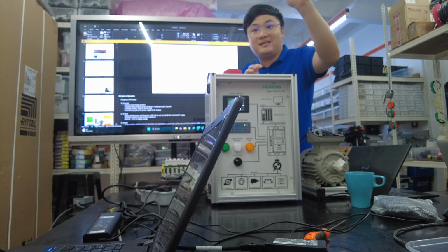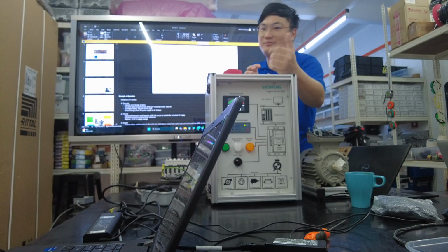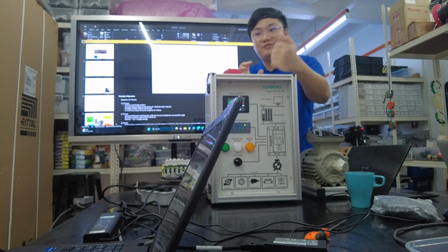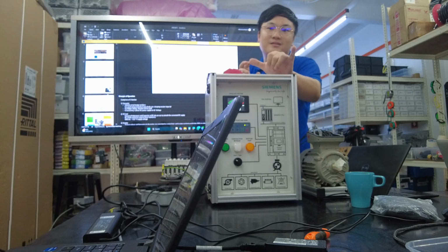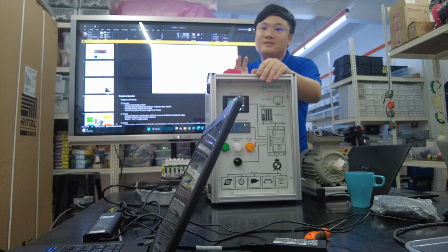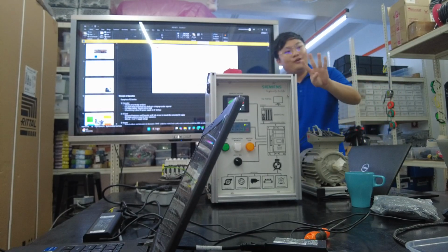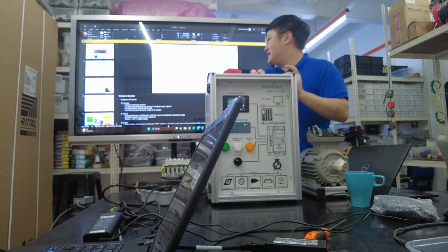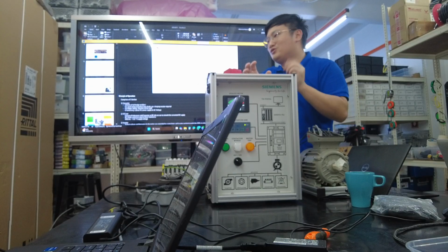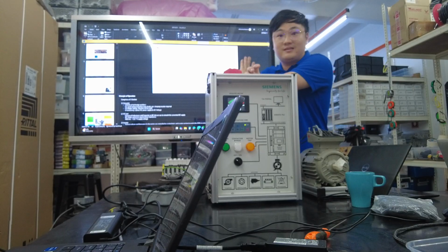The higher the hertz, the better the control, but also the higher the energy consumption. A standard Siemens inverter can usually go up to 16 kilohertz, but commonly our maximum setting is 4 to 8. Very seldom do we set up to 16. The general default setting is usually 4,000 hertz. Sometimes we might need to tune it, but most of the time for general applications there is no need to change the frequency setting.